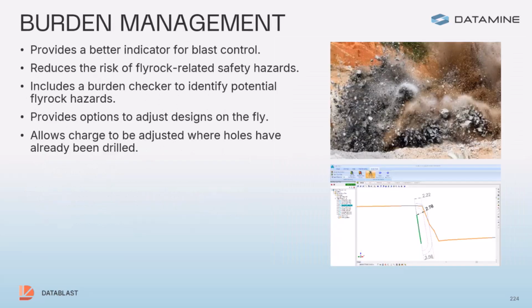Okay, now one other feature we have is burden management in Designer. Burden management is a way of recording if you are likely to blow out the hole from the side onto the face burden. It's again an important indicator of blast control. We've had this in for a while, and a lot of people use this as a report to show that they've complied with checks, to ensure that they have shifted holes or changed charging so that the actual blast radius is not going to go outside of the side burden or at the top of the hole.